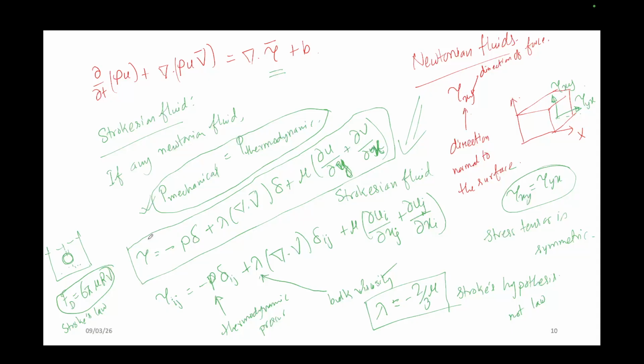So that is not necessary. Actually, the thing is the difference between Stokes law and the Stokes hypothesis. The Stokes hypothesis is basically based on this Stokesian fluid, where he has discussed what the tau should be. So he just elaborated this tau. For this he said that to elaborate this tau, I have found out that this lambda equals minus 2 by 3 of mu. That is his finding. And so he just gave the hypothesis which may not be universally true.